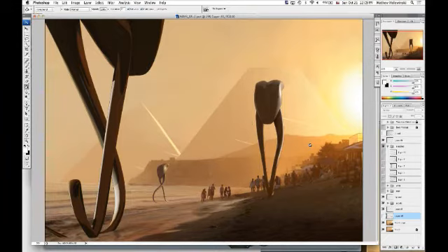But I go back and forth, and the other good thing is, to get the colors to match with the whole thing, in Form Z you can import a version of this image with the background colors that doesn't have the model in it yet. You can use it as the lighting environment while you're rendering. And so you get the color reflections of the environment in the model. And when you then put the model into the illustrations, the colors are already much closer than before.